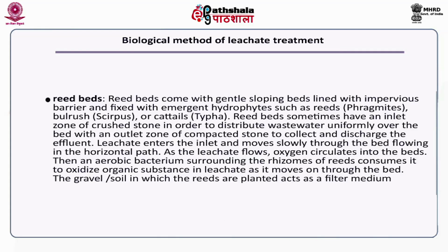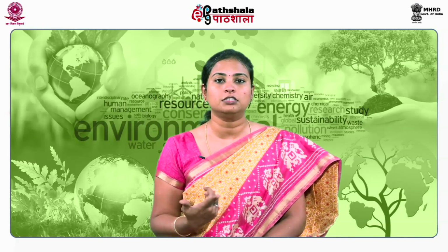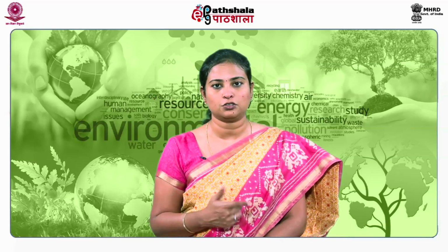The next type of unit is the reed beds. Now, reed beds, you might have heard about the constructed wetlands. So, it is similar to that. Reed beds come with a gently sloping bed lined with an impermeable or impervious barrier, and they are planted with emergent hydrophytes like reeds such as phragmites, bulrush, cattails, that is typha, etc. Typha and phragmites are the more popularly used species in constructed wetlands or reed beds.